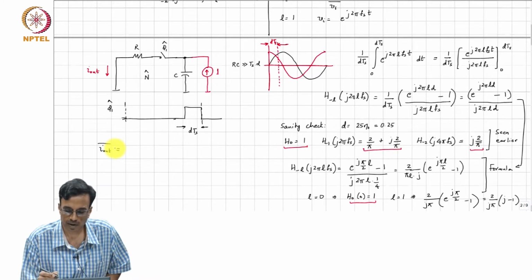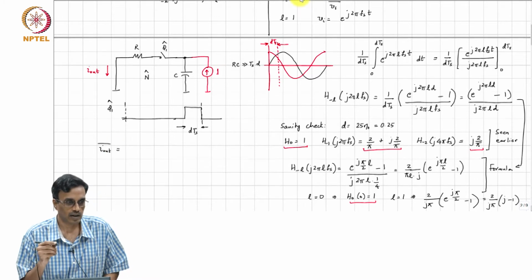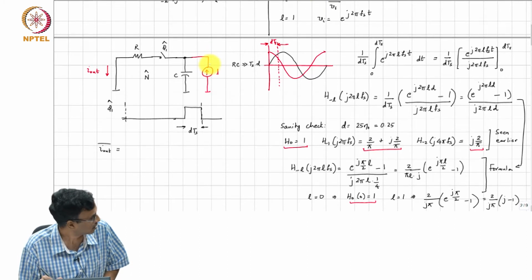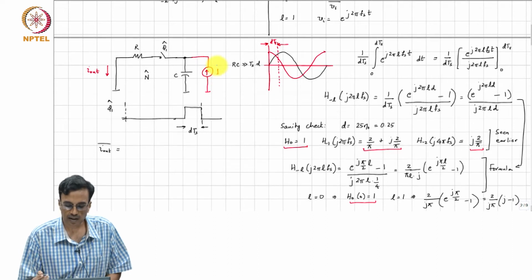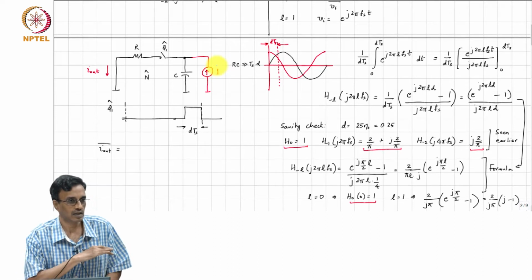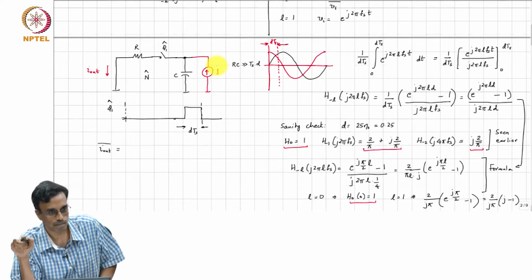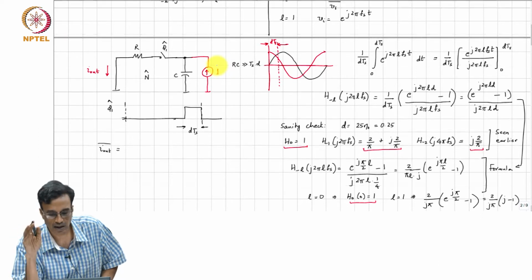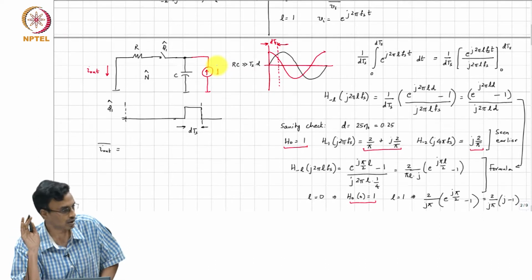Okay, let me lead. On that period, only that period current is injecting. The DC current injecting into the capacitor is there for all time. It is a constant current. It is going on injecting regardless of whether the switch is open or closed, right.